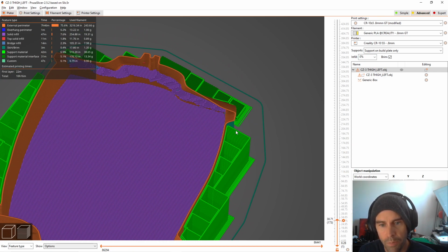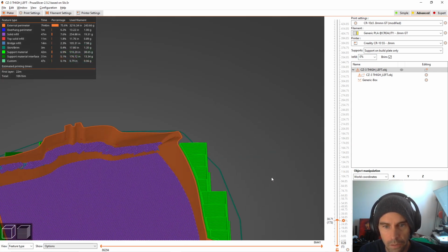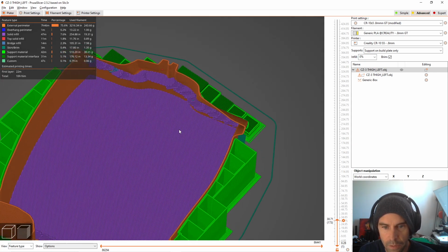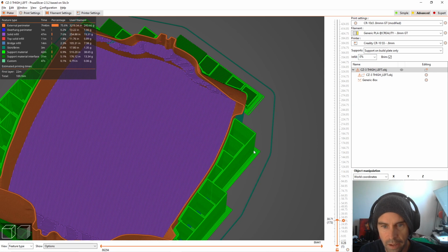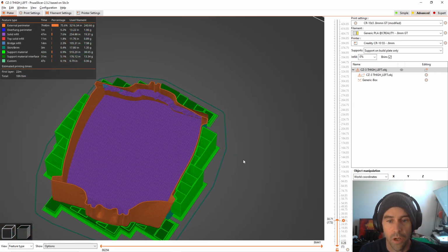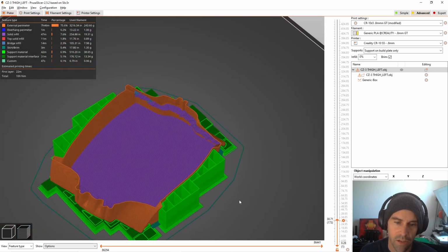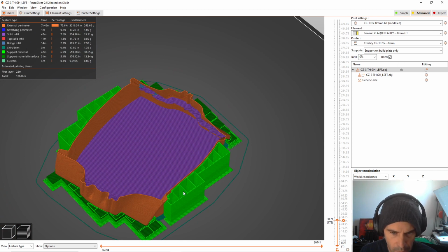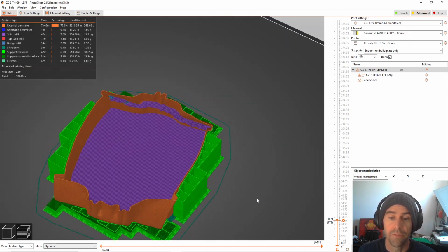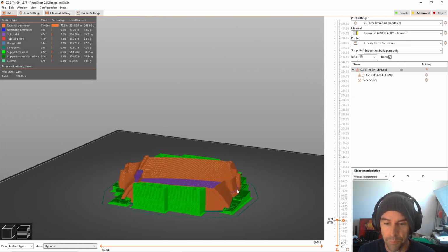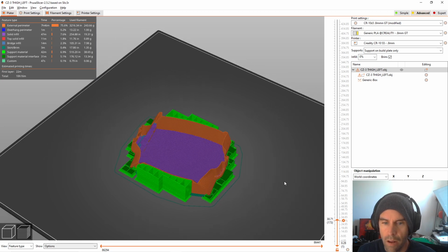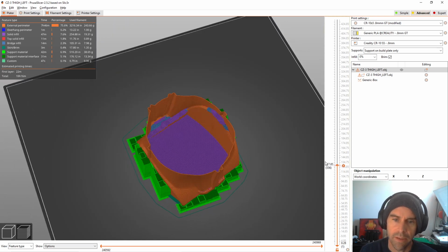But you can see that the support material is literally as thick as the print because I'm using the same amount of thickness because it's one layer. So doing this too heavy it's overkill. I could go probably even less than this. I'm guessing 15 millimeter would be fine for this. It would do the job for me. But that's that. Let's scroll to the top here.